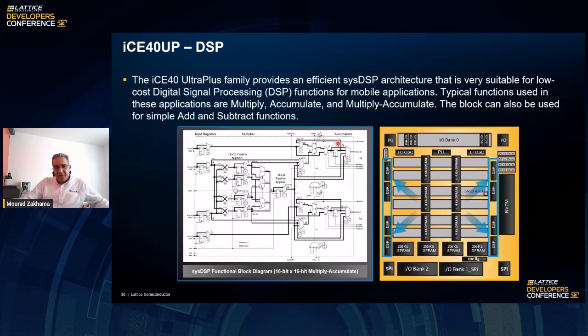And as I said before, implementing this in logic could be very expensive. One 18 by 18 DSP could be using up to 500 logic cells. So by having this hardened function, you obviously optimize the number of resources that are used and have the rest of the programmable logic area to tune to your need or to implement your own logic.